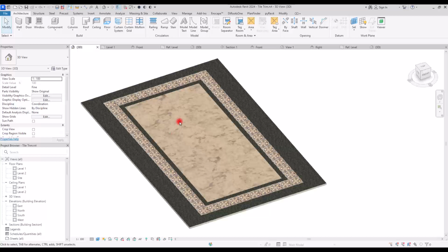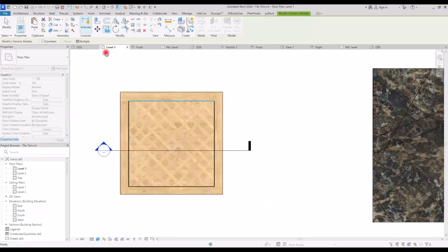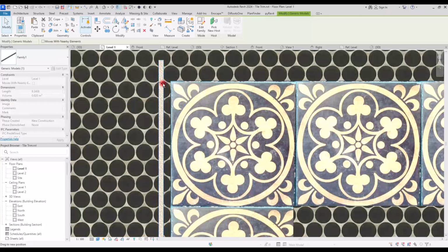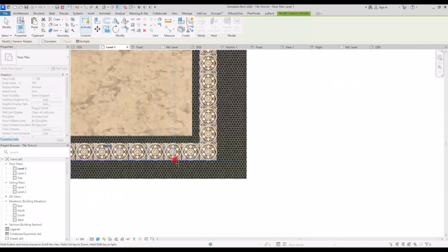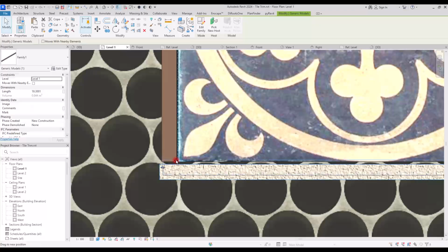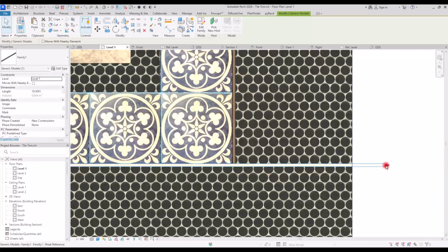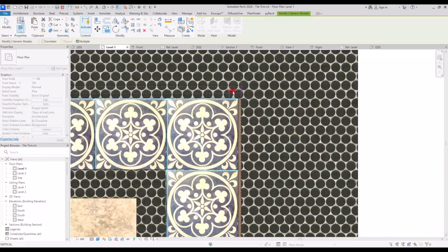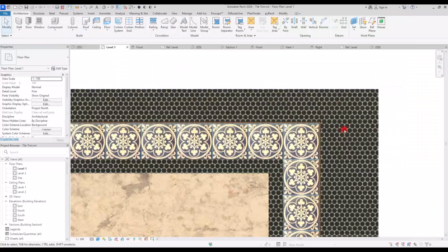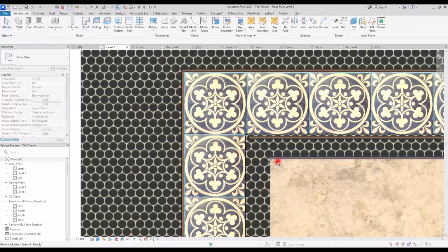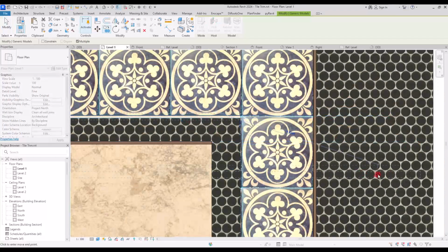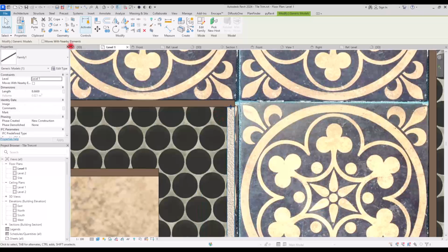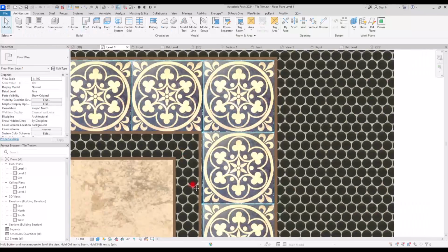I'm sure you have seen these type of floors on corridors, on lobbies, and maybe some unique spots. And now you can just simply create them yourself with the materials that you want. To finish this, we can add some tile trims around the borders, maybe inside the floor, inside each material, and the stone, the tiles. I have exaggerated a lot on the size of these floors, the thickness and the dimension, lengths and widths, so we can model it better.